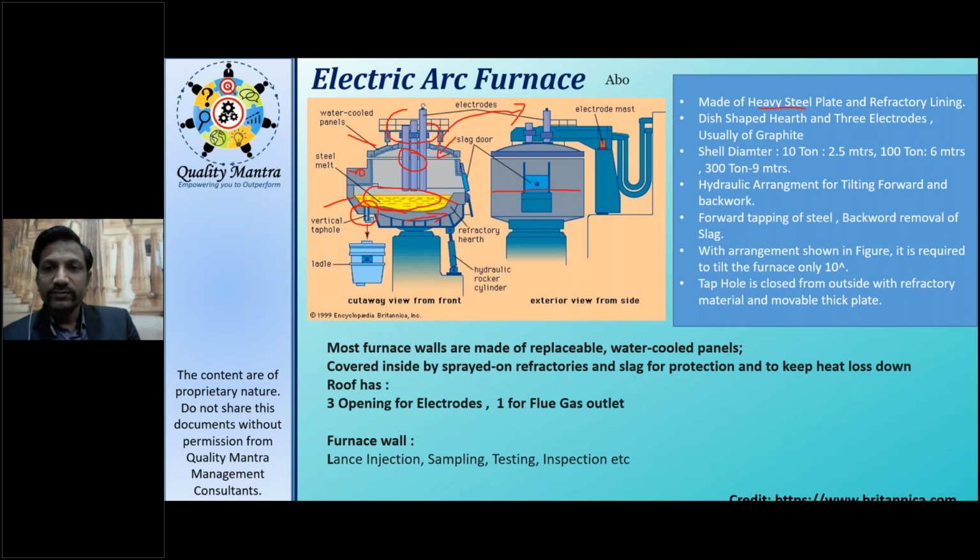Okay, yeah. So the basic steel electric arc furnace is made of heavy steel plate. The structure is made of heavy steel plate, and then inside there will be a refractory brick lining. It can withstand high temperature and erosion by the molten metal. After this, basically you can divide it into 3 parts: the hearth, the side walls, and the roof. The roof can be removed totally.